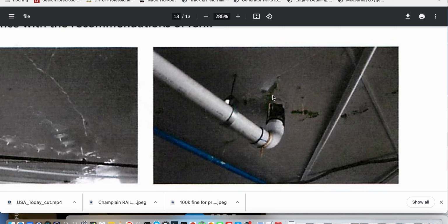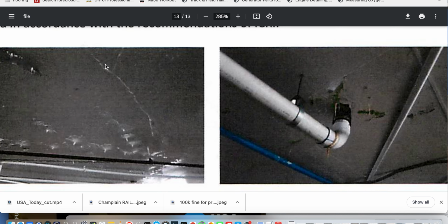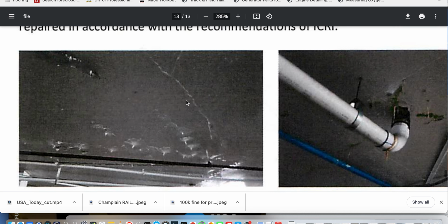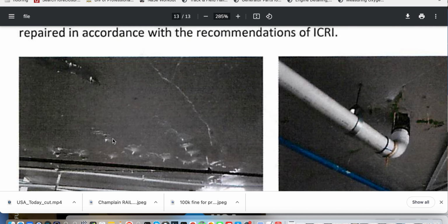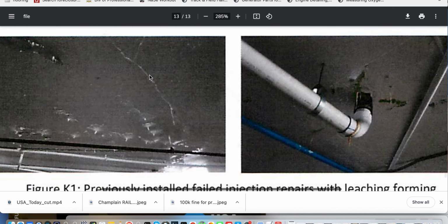And what do we have here? Green. This is a 2018 report. This means this was done before 2018. That building next door was about 2016. It was claimed to be built or something like that. Well, they had efflorescence issues going on before then. The pilings weren't, unless they're claiming the pilings did all this instantly and cleared all this efflorescence in 2018, 2 years later. This is like 3 years plus efflorescence, I believe.